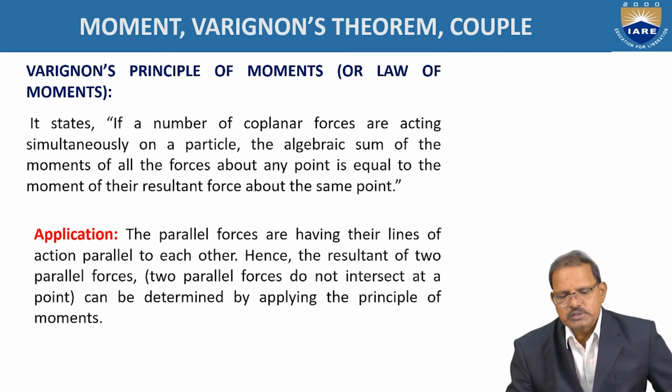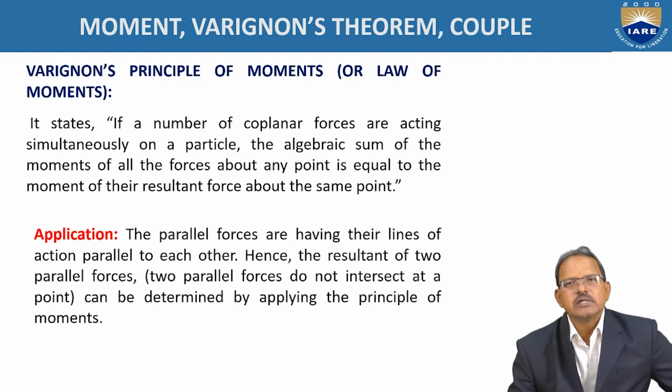Varignon's principle of moments, also called the law of moments, states that if a number of coplanar forces are acting simultaneously on a particle, the algebraic sum of the moments of all the forces about any point is equal to the moment of the resultant force about the same point.